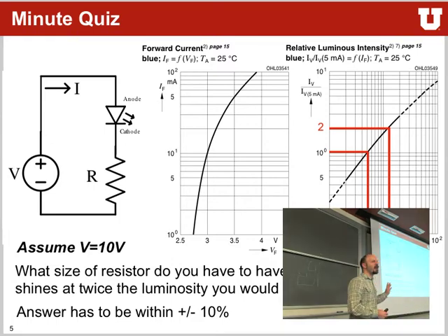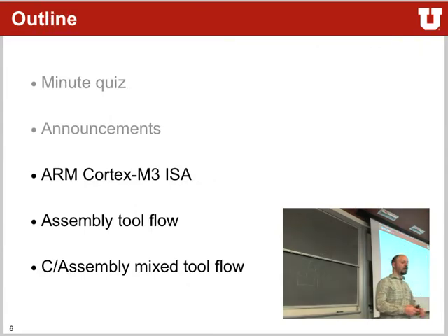You will also find out that with LEDs, it really doesn't matter that much what your resistor is. Plus or minus 10, plus or minus 20% is absolutely fine. The LED will still light up most of the time, just sometimes a little less bright than others. The tricky part is when you have LEDs of different colors. If you want them to shine at about the same brightness, you have to adapt the resistors to different values. Or else you will have a blue LED that is extremely bright and another LED that's not bright at all.